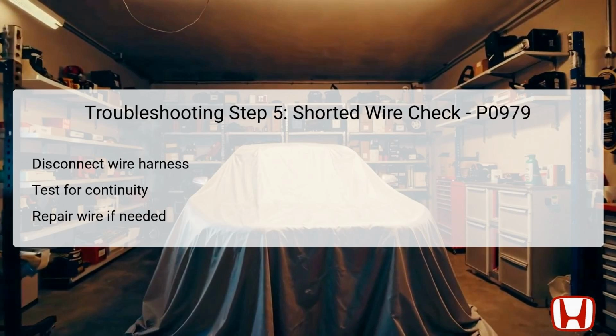The key objective here is to determine if continuity exists within the SHC wiring. If continuity is detected, it implies there is a short to ground in the SHC wire between the shift solenoid wire harness and the PCM. This will require immediate repair and verification steps to ensure the circuit is functioning correctly. On the other hand, if there is no continuity, it suggests that the SHC wire is intact, thus prompting you to proceed to the next troubleshooting step.